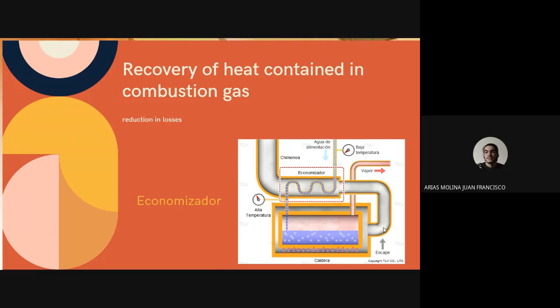The increase in efficiency of the boiler economizer group occurs due to economizer factors. The chimney economizer is commonly used for heating water on the simple types. It uses the thermal energy of the exhaust gas in the process of heating the boiler feed water and reduces the amount of fuel needed.